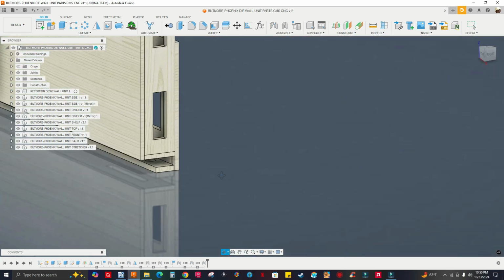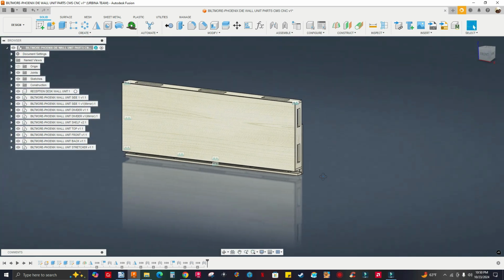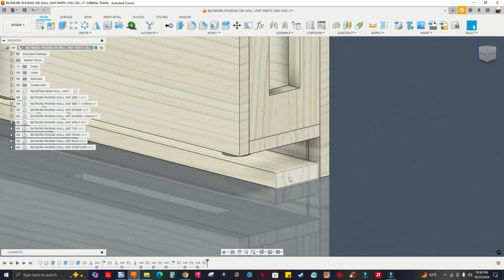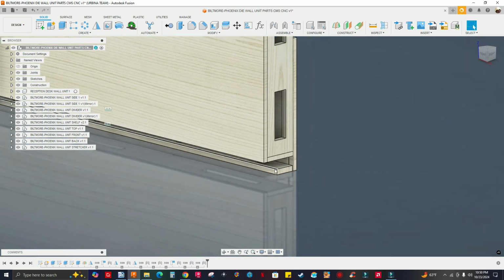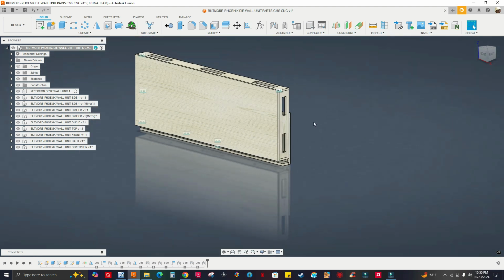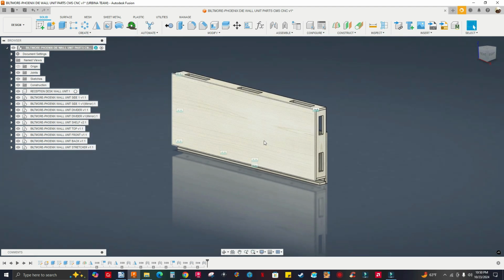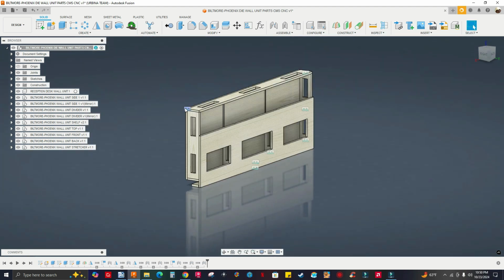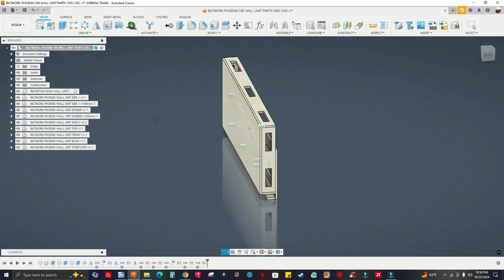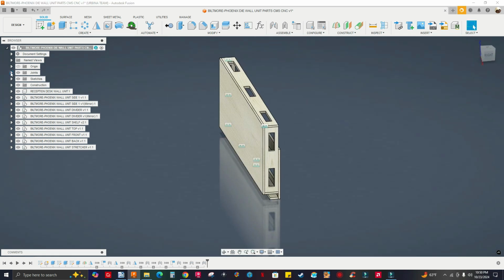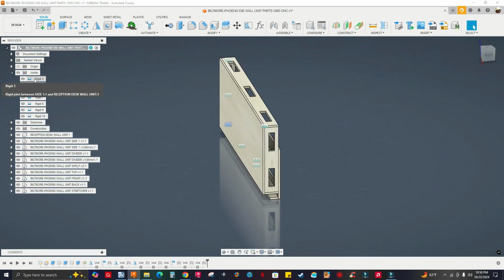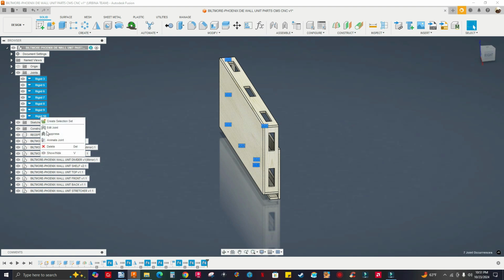All right. I can just position this piece anywhere. I just need this piece because I'm gonna nest this entire unit, right? Now I don't want to see these joints all over the model. So I go to joints, click on this arrow drop down, select the first one, rigid 3, hold down the shift key on my keyboard, select rigid 10, right click, hide, and they're gone.